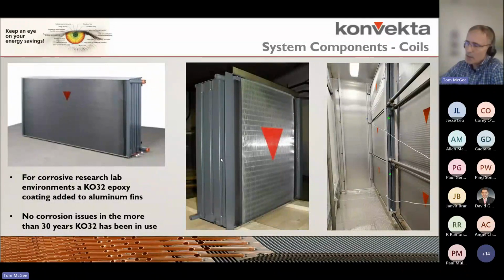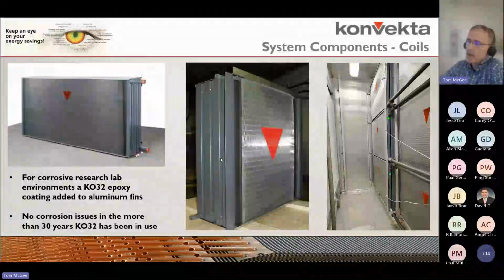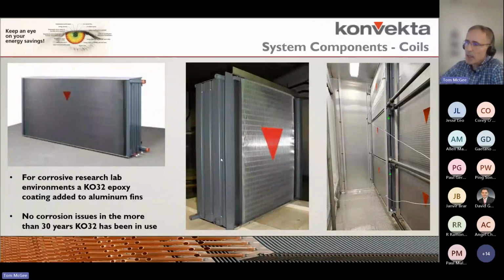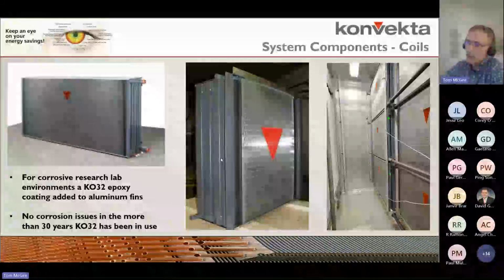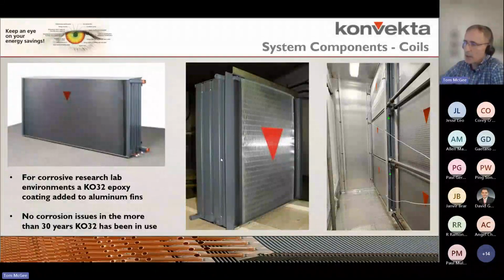You can see the gray header, which is a steel header. It's coated with an epoxy coating. We also do this on a pretty regular, consistent basis for coils that go into exhaust air streams that have the potential for corrosive elements. If we're close to salt water, we would apply it to the fins, not only in the exhaust, but the fins in the supply as well. And very little degradation of energy transfer.